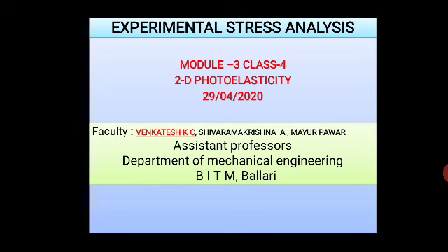So, in the analysis of isochromatic patterns, it was shown that the principal stress difference between sigma 1 and sigma 2 could be determined directly, and that of maximum shear stress could be determined provided that the two principal stresses are of opposite sign. Also, we had that the free boundaries,